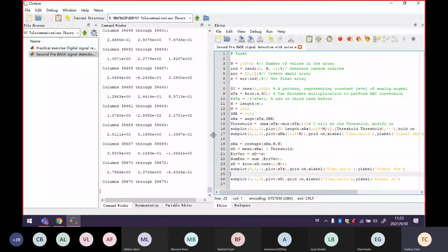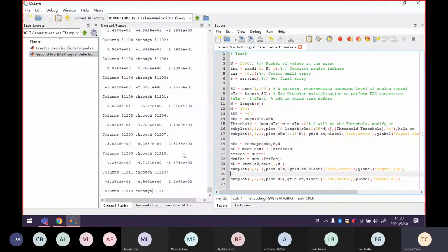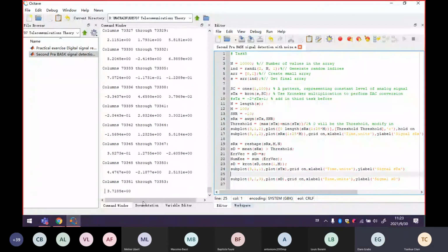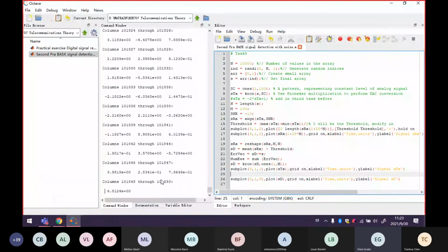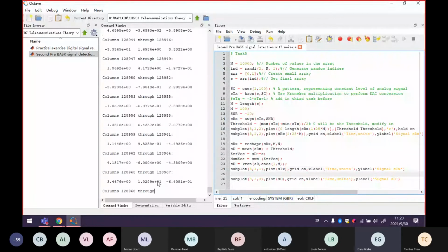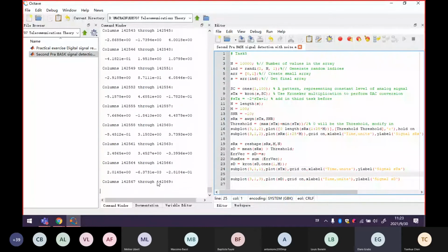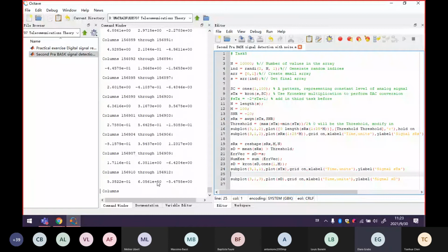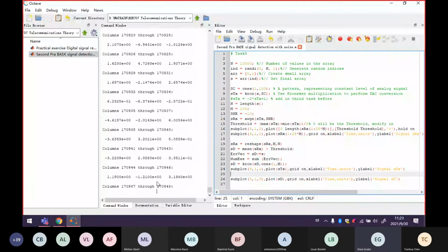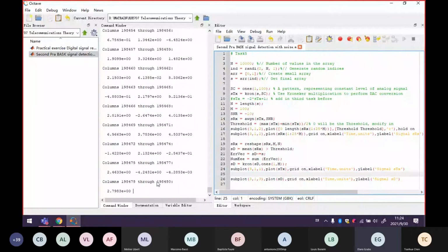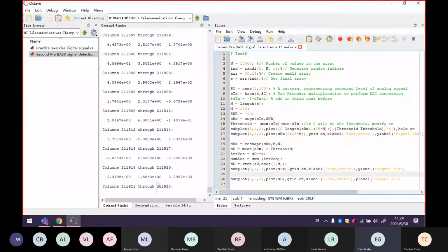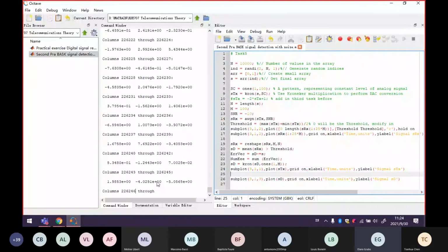Yes, for my laptop it will cost some time, I think. But you can speed up the process if you put semicolons after each command, especially when we have these 10,000 symbols. I can see that, for example, line 19 is not finished with a semicolon, and this output actually is what takes this long time. This printing on screen is taking so much time, but the command itself works very fast.